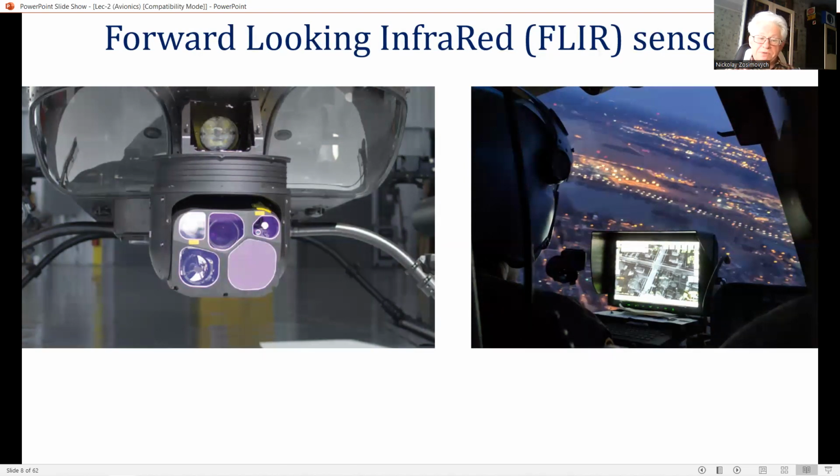The TV raster picture generated from the FLIR sensor video is projected on the HUD and scaled 1:1 with the outside world, enabling the pilot to fly at low level by night in fair weather. This provides a realistic night attack capability to a relatively simple day ground attack fighter.